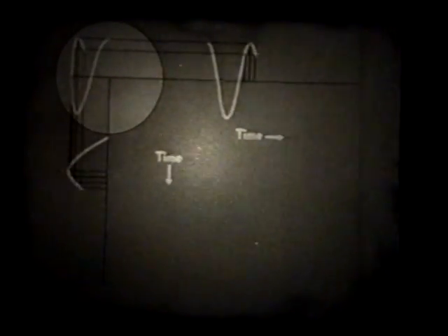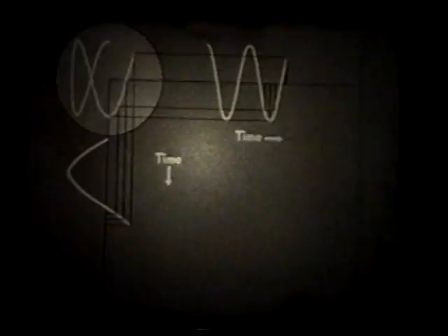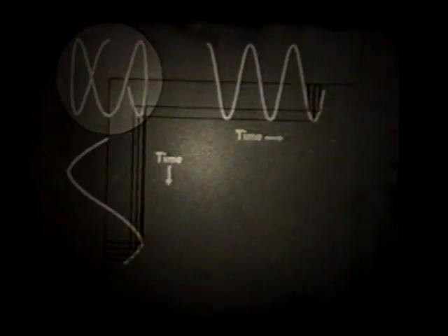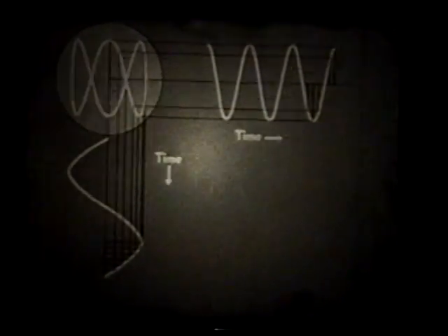If 2 different frequencies are applied to the 2 different sets of plates, we get another type of wave on the screen. This figure, for example, is the result of a frequency ratio of 1 to 3, with the horizontal and vertical voltages 90 degrees out of phase.